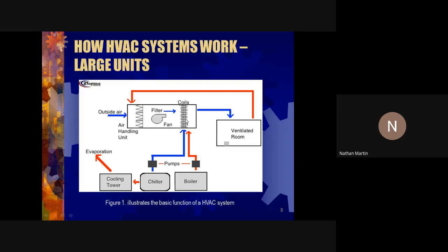So under the dashboard would be your coils, and the hot water will pass through those coils. Now, if we are not supplying heat, then we are going to lock off the hot water from passing through the coils. If we want to supply heat, then what we're actually doing is turning on the flow, or enabling the flow of hot water through the coils, for us to be able to heat or warm inside the car.